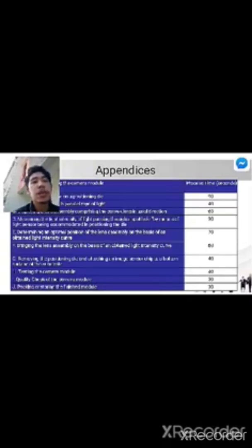In order to achieve our goal, we have to study the assembly line balancing from the given data and follow the steps. Before we begin solving our problems, there are a few things that we need to pay attention to. First, make a precedence diagram and determine the cycle time. Using the largest operation time heuristic, determine the most efficient production line. And last, determine the line efficiency and the smoothing index.